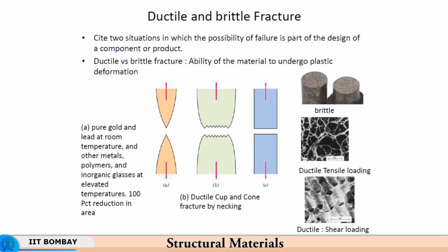So since it is an intergranular fracture, you see that different facets of the grains are shining, meaning they reflect light very well. That is the reason why the brittle fracture looks very bright, whereas the ductile fracture looks very dull. So the reflectivity of a brittle fracture is because of the intercrystalline nature of the fracture.